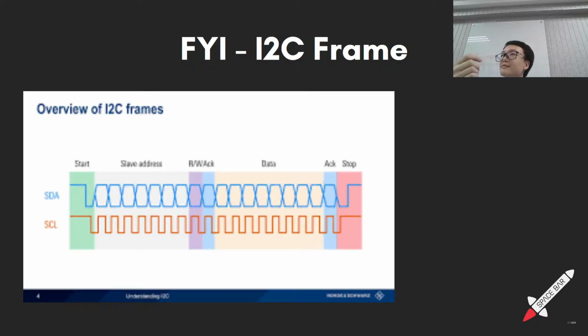It's because of I2C's nature of one master, multiple slaves architecture, so slaves and devices are interchangeable, and the master is usually the ESP. And because of this nature, it has open collector outputs. So the ESP has an open collector output on this, and the device also has an open collector output or input depending on whether it's receiving or sending.